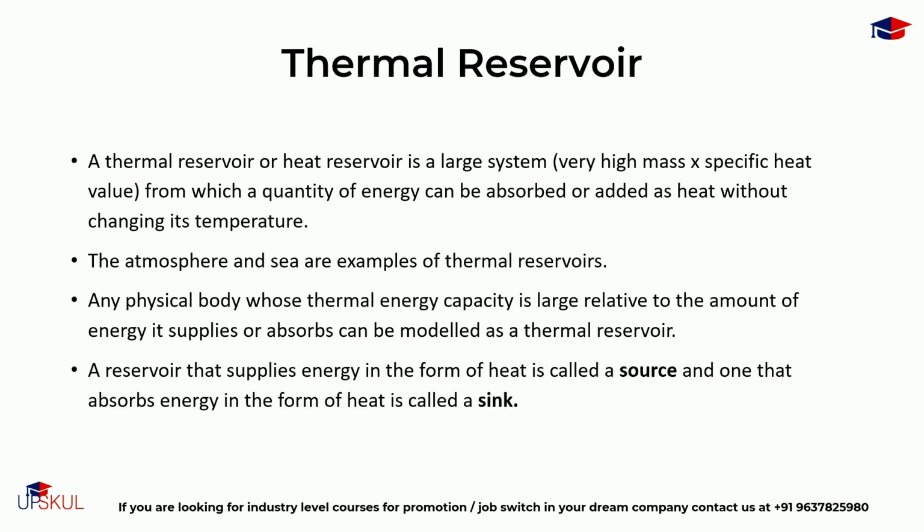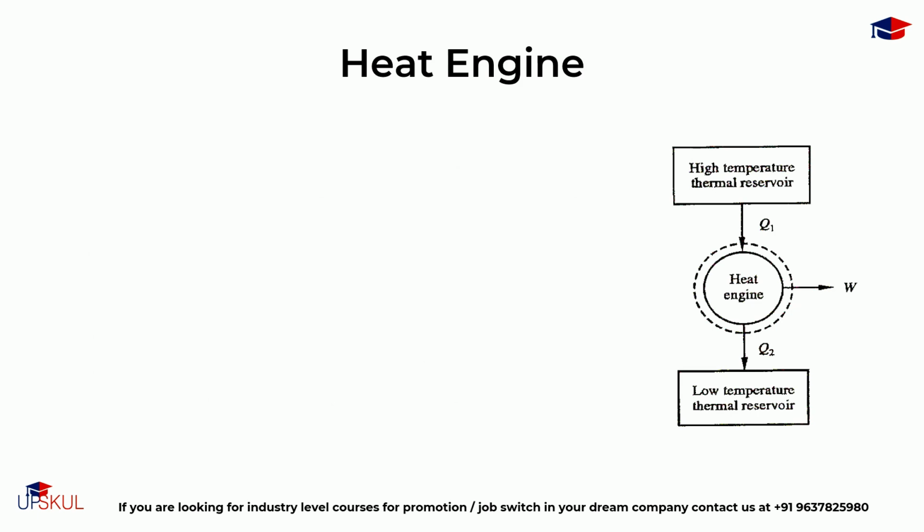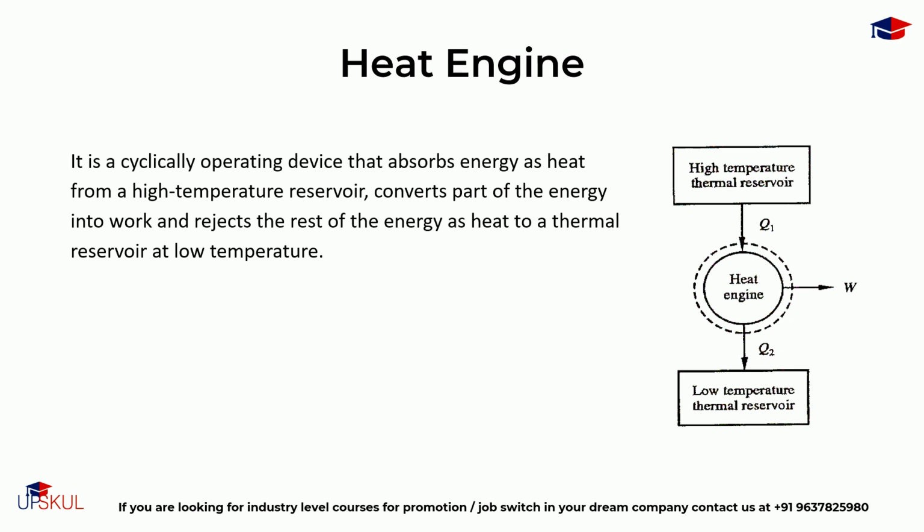A reservoir that supplies energy in the form of heat is called a source, and the one that absorbs energy in the form of heat is called a sink. Heat engine. A heat engine is a cyclically operating device that absorbs energy as heat from a high temperature reservoir and converts part of the energy into work and rejects the rest of the energy as heat to a thermal reservoir at a lower temperature.